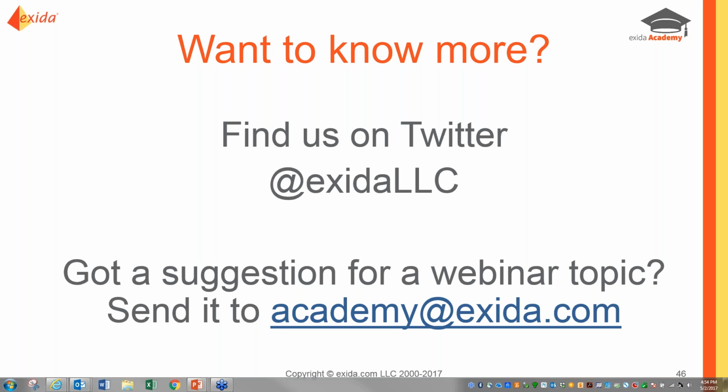What degree of independence is recommended for the CFSP, CFSE in verification and validation of SIFs with a SIL 3 requirement? There actually, I believe, are some statements within the standard for a SIL 3. Certainly for those higher integrity systems, you want a higher level of separation between the people who do the design and do the internal verification and those that do the assessment. If you're going up to a SIL 3, you want more separation associated with that, and it's good to have more than one set of eyes on the process.